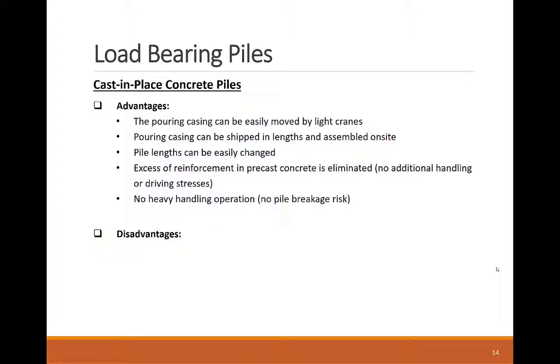The right amount of steel reinforcement is used in this case compared to excessive reinforcement in precast concrete. There is no need for heavy cranes again, as the piles are constructed in their holes and not handled on the surface. And whole piles can be constructed with not much lead time, allowing for flexible projects with quick design changes. Cast-in-place still imposes challenges.